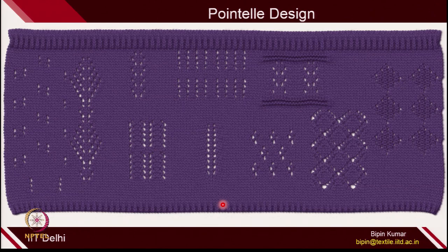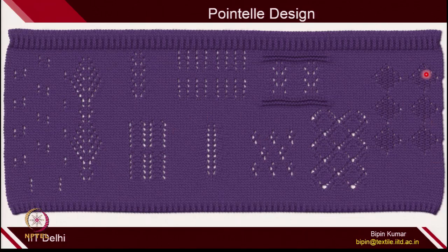Pointelle design gives you a lot of flexibility to create some kind of lacy pattern. You can see there are a lot of patterns which you can create. Everywhere some of the needles will be shifting either left or right. The loops will be shifting to the left column or right column, and if you keep doing it, a beautiful pattern can be created on the fabric surface. Again, it depends entirely on the imagination of the designer. Some of the designs, for example this one, are very complicated.